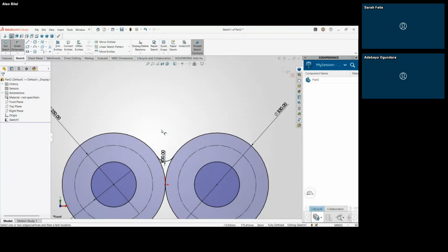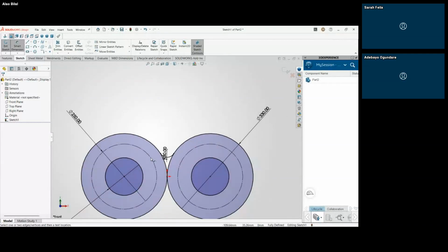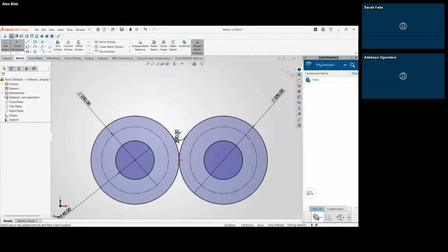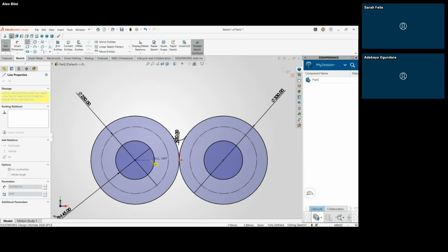Yeah, so another easy thing that we can do is using our mirror function. There's no need to be afraid to use your mirror function. It's very much available for you. You can just use it, but you have to create a center line. That's a construction geometry that is horizontal at the middle, to allow it to create that point and mirror this arc by this point.